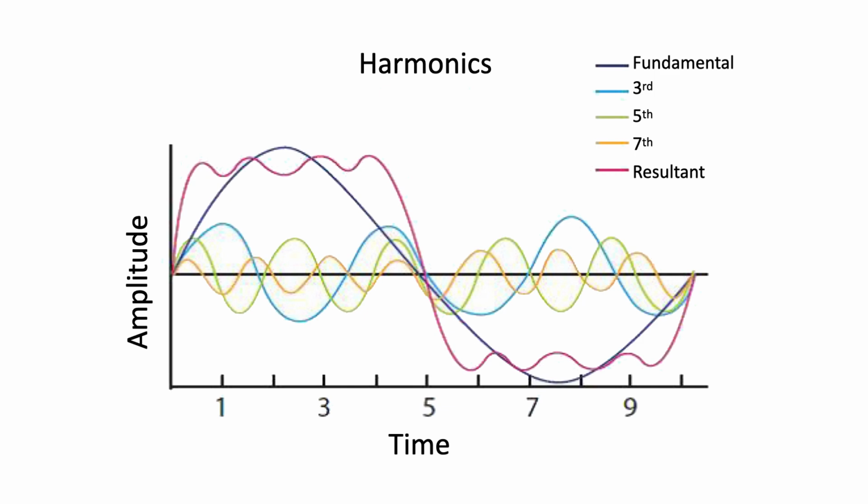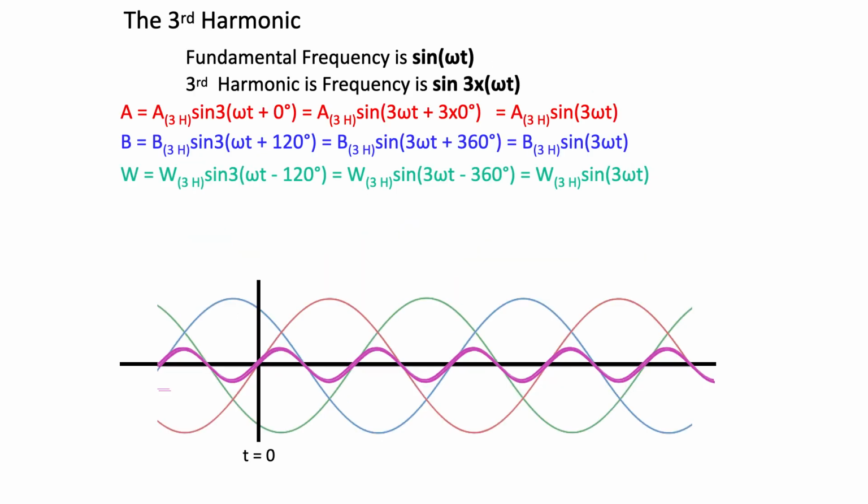However, just an understanding that complex waveforms, if repetitive, are made up of the fundamental frequency plus integral harmonics, or multiples of the fundamental component, is enough. When analyzed, the third harmonic frequency of any sinusoidal wave is equal to 3 times the frequency of the fundamental frequency, and therefore, in a three-phase balanced system, the third harmonics of all three phases are in phase with each other.